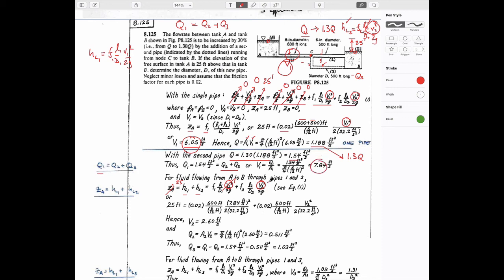The only thing that we don't know is the part that comes between this, which is the same as calculating what the head drop is between here and here, and prescribing that the flow velocity conforms to that head drop. This equation gives us exactly that, written by continuity. So we don't know what V2 is, but we know everything else in this equation.